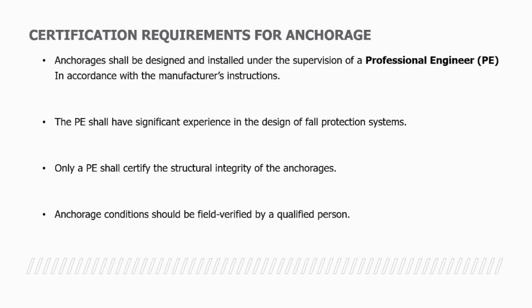On to the next part, certification requirements for anchorage points. The anchorage points have specific information that they are required to entail. Anchorages shall be designed and installed under the supervision of a professional engineer in accordance with the manufacturer's instructions. The PE shall have significant experience in the design of fall protection systems. Only a PE, a professional engineer, shall certify the structural integrity of the anchorage points, and the anchorage conditions should be field verified by a qualified person.